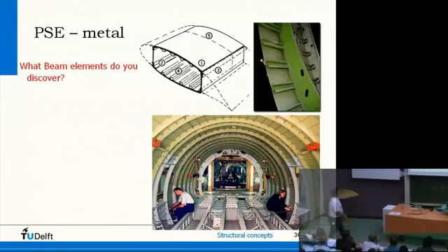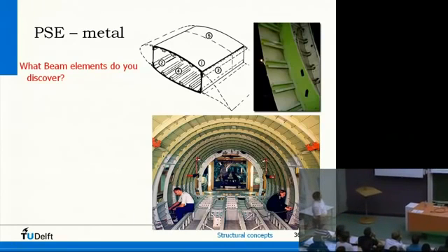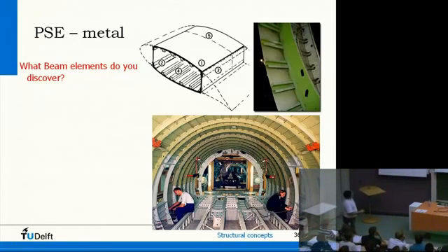Well, just a few pictures to show. Here you see, for instance, a wing box. This rear spar has a girder here and a girder here, and this is its web plate. You also have a front spar. At the same time you see all these stringers. As I told you, these are also kind of beams. Upper flange here, and these are so-called hat stringers, so they have two lower flanges, and these vertical areas are two web plates.